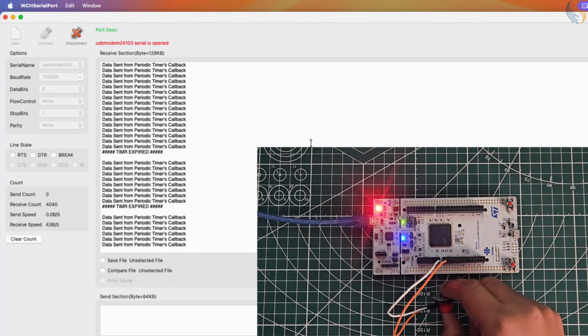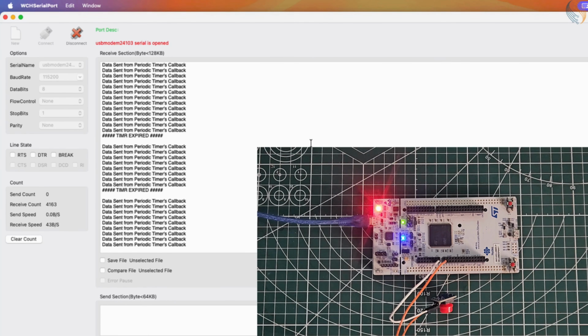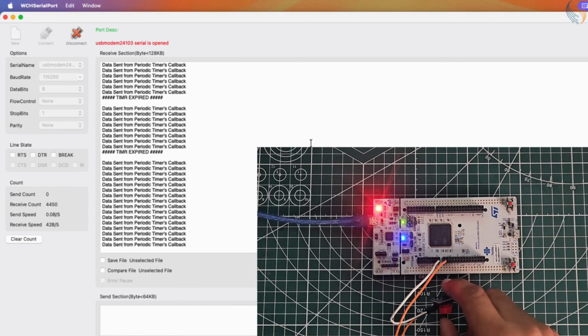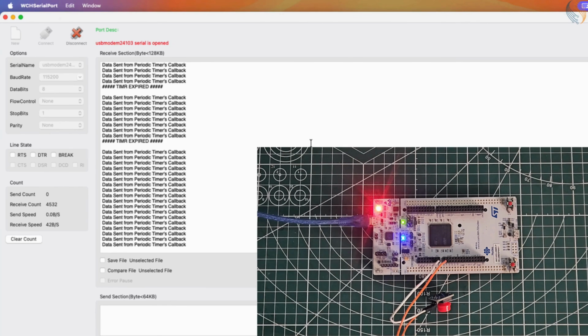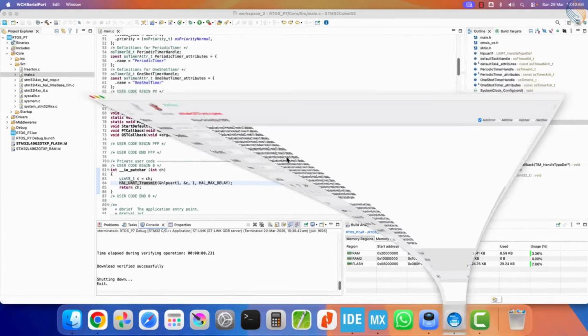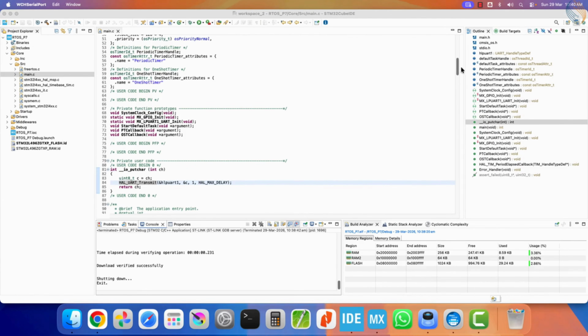What happens if we keep pressing the button before the 5 seconds are up? Every time the button is pressed, the timer start function is called again for the one-shot timer. This does not create a new timer or stack multiple timers on top of each other, it simply resets the existing one, pushing the expiry point forward by another 5 seconds from the moment of the latest press. As long as we keep pressing the button within the 5-second window, the timer keeps getting reset, it never expires, and the callback is never triggered.